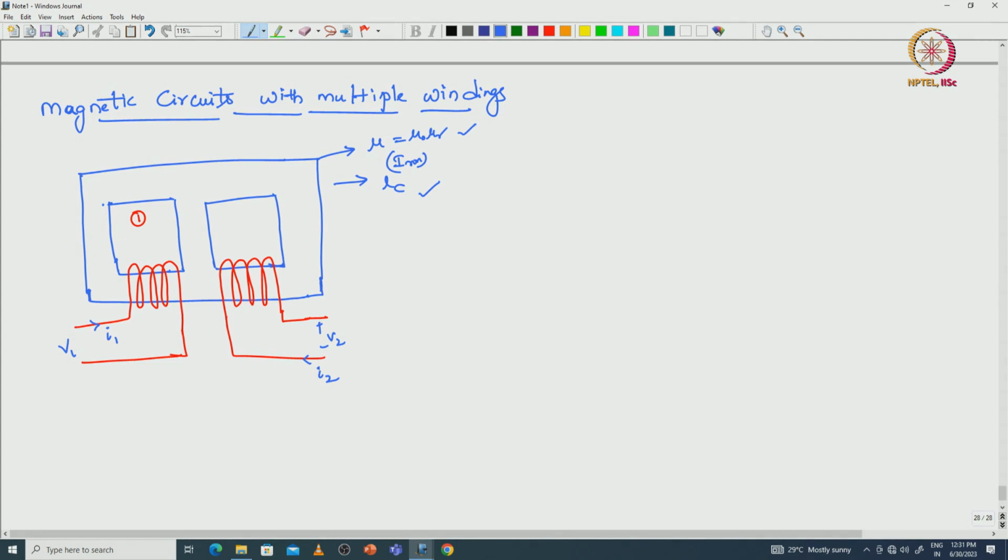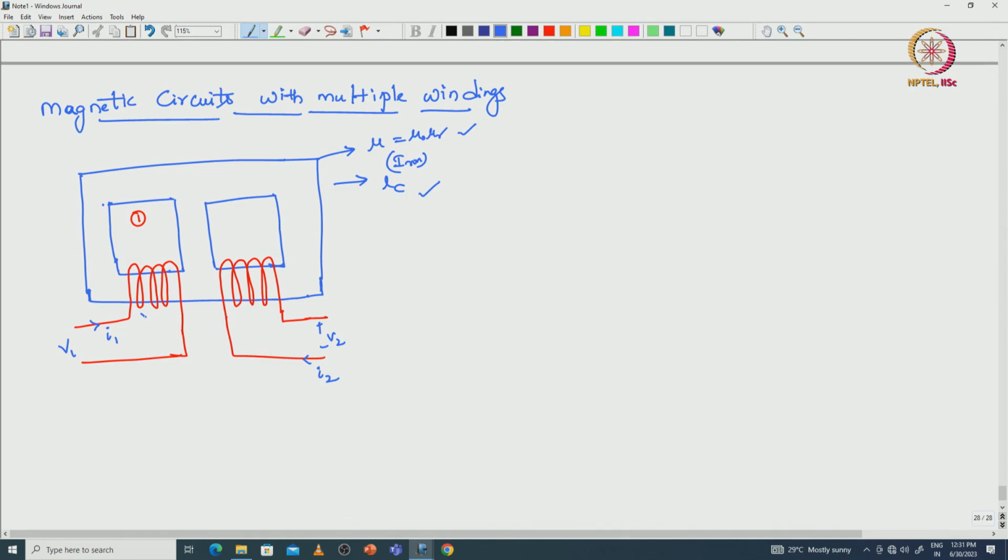Apply the thumb rule and find the magnetic flux, or magnetic fields, the same way we have done so far. In both coils, the flux is in this direction with respect to the thumb. Fingers I am representing with current, B fields with the thumb. We can see here the current is entering this side, going in and coming out in this fashion, then the flux lines are in this direction. B fields are flux lines. Flux lines we can represent with flux.